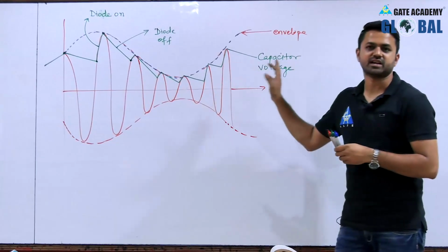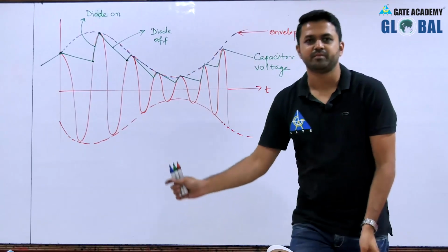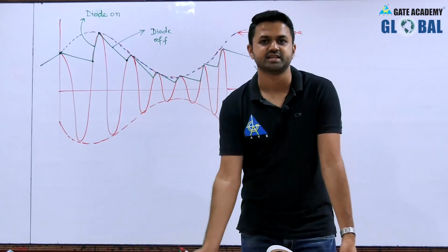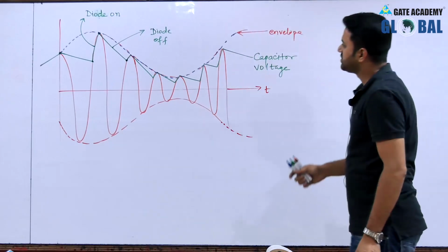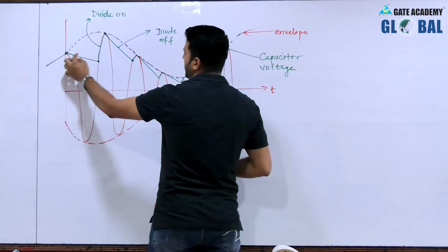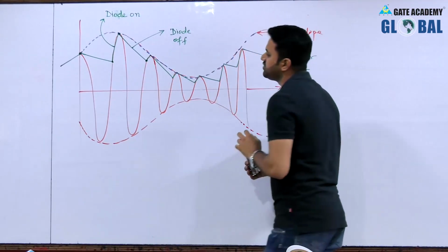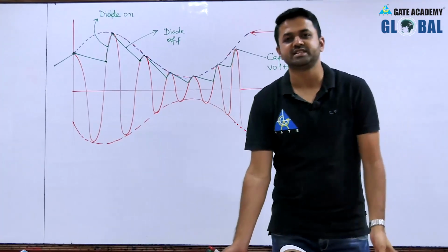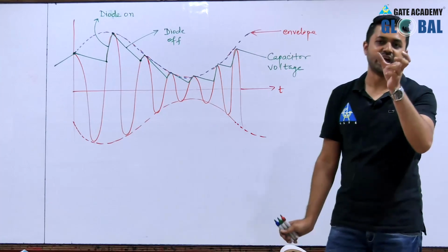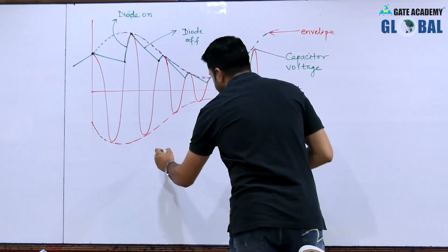During the positive half cycle of the input, the diode is forward biased and the capacitor is charging, and in reverse bias it is discharging. To follow the actual envelope of this AM signal, the capacitor voltage will have some time constant, or the circuit has some time constant.